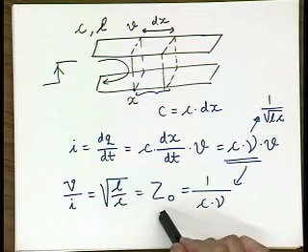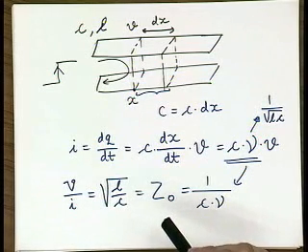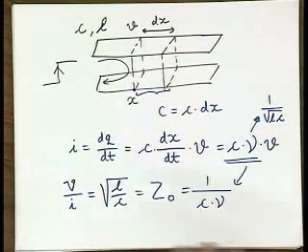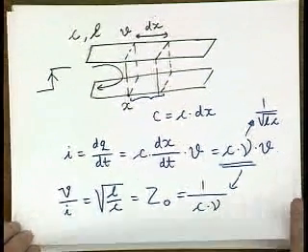And this is really important and really interesting because you remember that with the RC model, we really cared about the length of the wire. Over here, we don't care. No matter what the length of the wire is, you always see the same impedance. And it is a really, really nice property, especially for the design of our driving circuits and so on. But there is a caveat there. You basically need to be very careful about impedance matching, as we will see in a second.